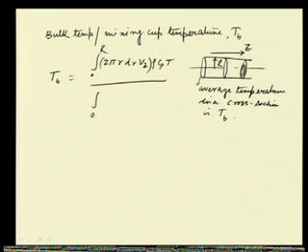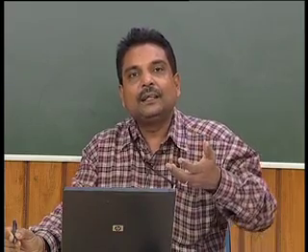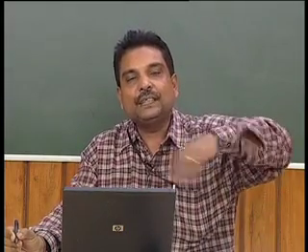This is divided by the heat capacity flow, again 2 pi r dr V z into rho and C p. So, this is the expression that gives the value of the bulk temperature or mixing cup temperature. Mixing cup temperature means that in a cup there is a fluid and the whole fluid is mixed up.